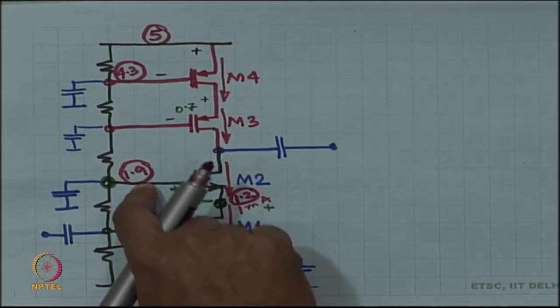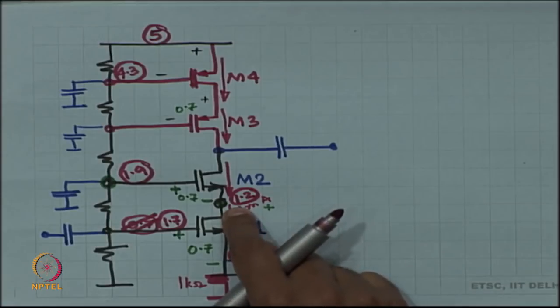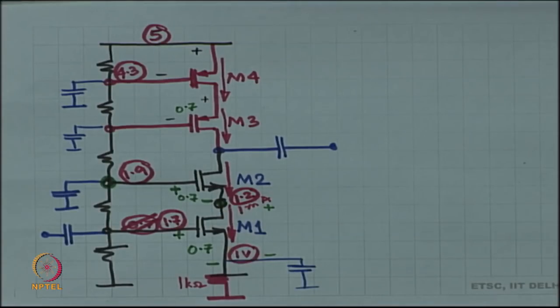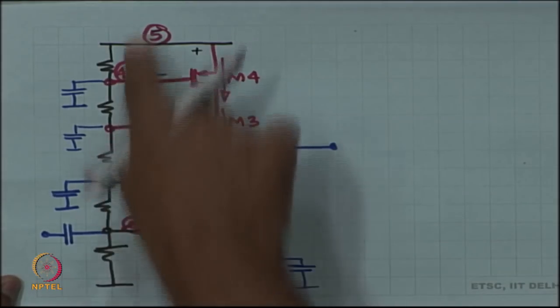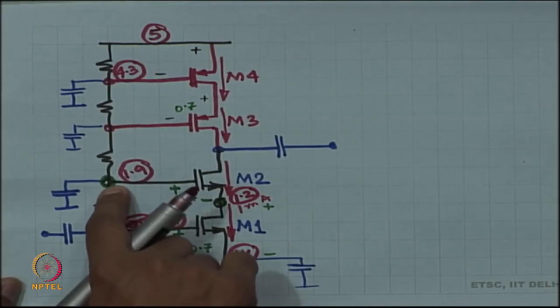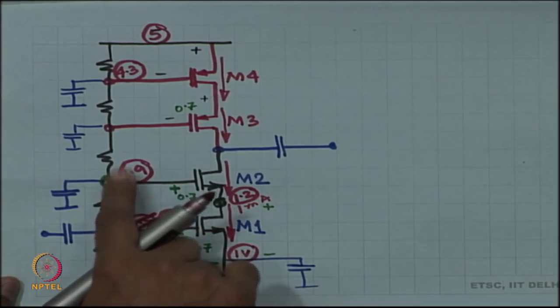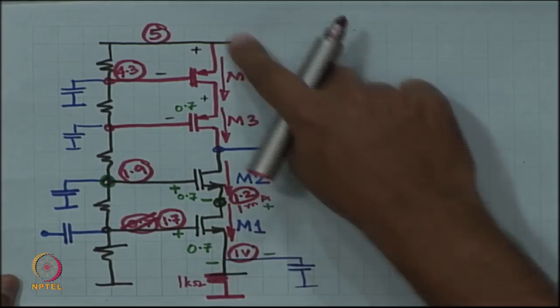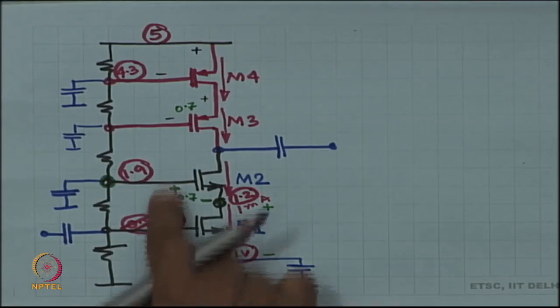So, this voltage at the gate is what sets the DC operating point voltage at the source, not vice versa. Design wise we went backwards when I am thinking of designing, but when it actually happens, this is what is enforcing. This potential divider will create 1.9, it does not have a choice. Now that it has 1.9 over here, it is going to enforce 1.2, so that it conducts the same current right through. Is this okay? All right, this is understood, I think.